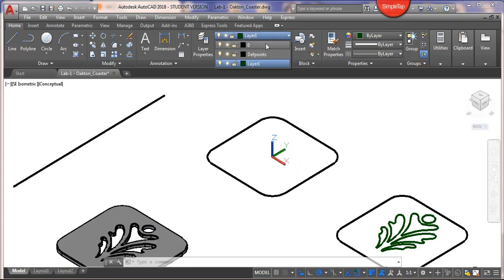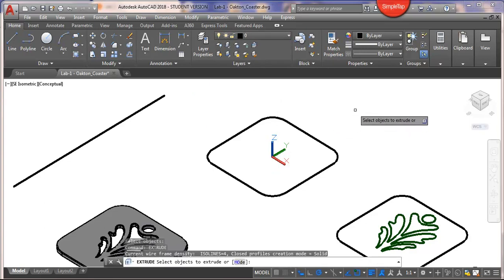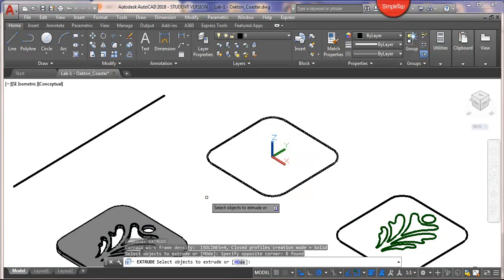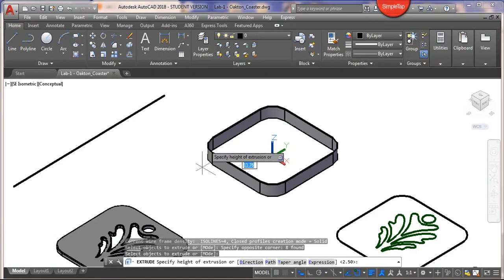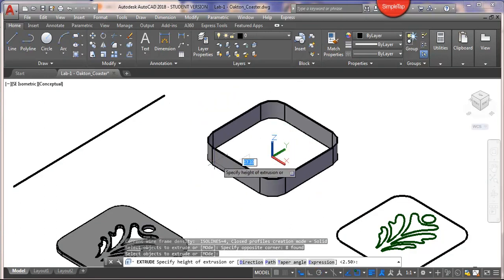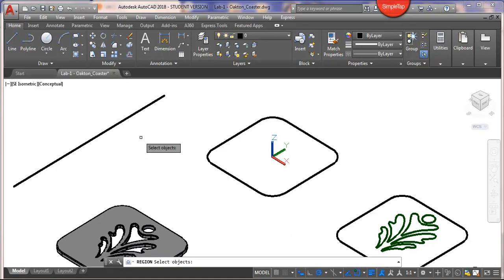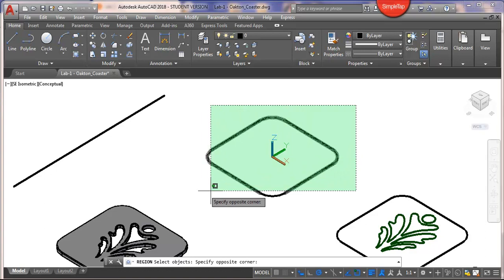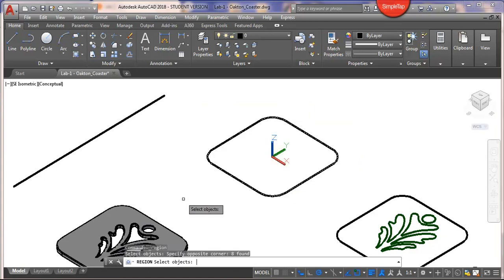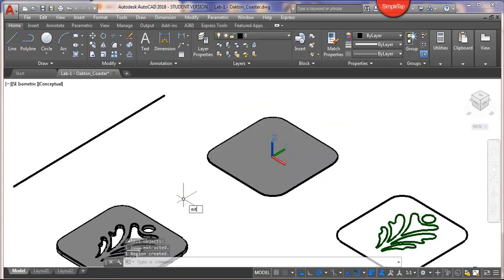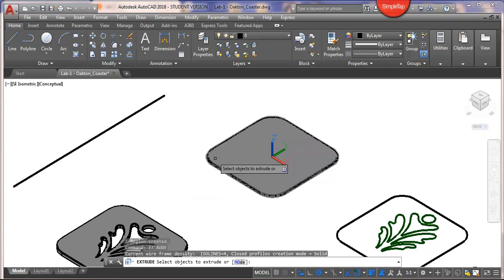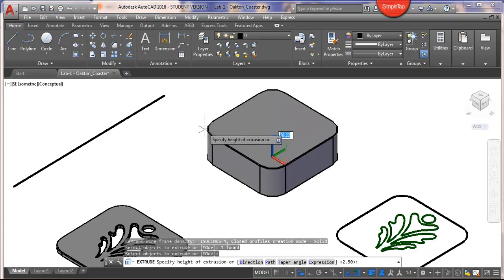They're all the same color. And I'm going to extrude this shape. Now you see how it only did the edge, and that's going to be a problem. I'm going to need to make it a region first because that would be a surface and it won't be good for 3D printing. So I've selected the region command. Now select that. Then I'll extrude it. I'm going to extrude this only a height of 0.5.